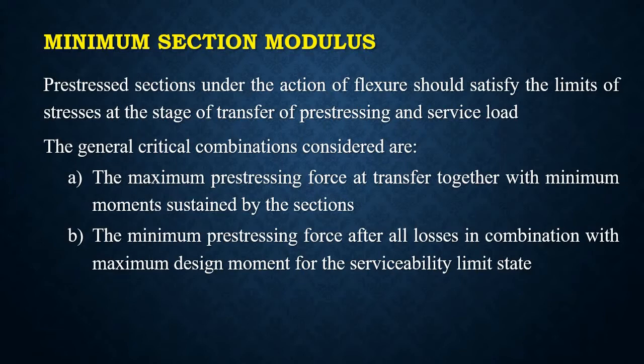The general critical combinations considered are: the first one is the maximum prestressing force at transfer together with minimum moment sustained by the section.